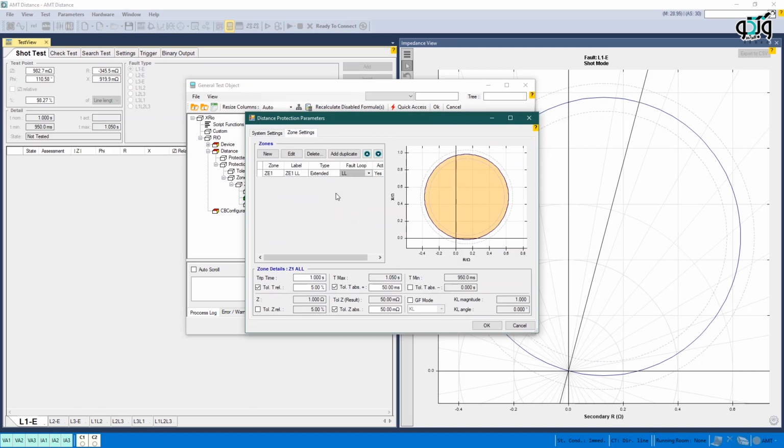You can use the active column to activate or deactivate a zone. Up and down options at the top of the table are used to move the defined zones. At the bottom of the page, there is a box including grounding factor, which makes it possible to specify a different single-phase grounding factor for each zone. However, this section is in progress and it's not ready for use yet.